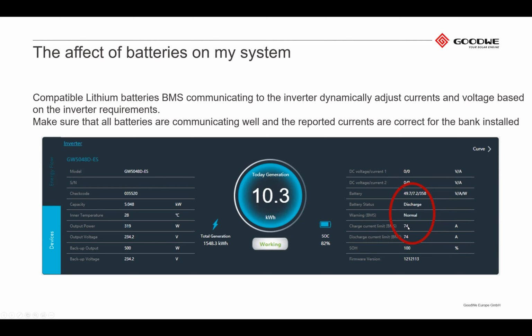I have seen it personally, that customers will install 4 or 5 batteries and leave the site, and it's no problem because load shedding happens every 3 months. So the system runs for 3 months, then load shedding happens and the inverter trips, and we come and look and we only see 1 battery here. So it's just one thing we have to keep in mind.